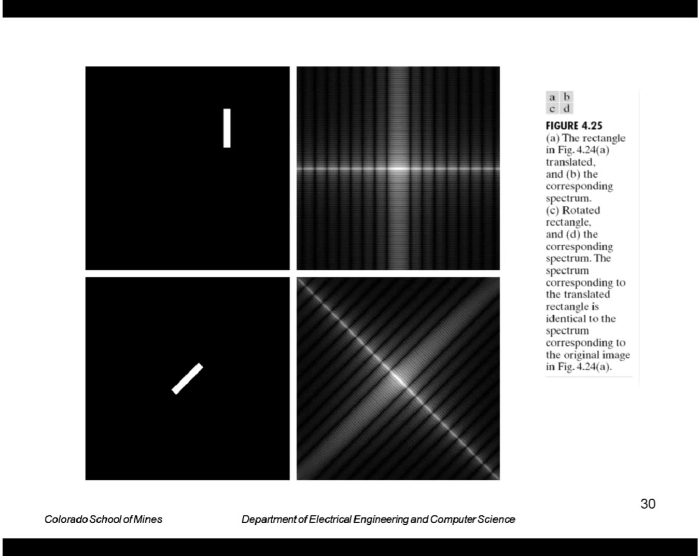So if we take the absolute value or spectrum, basically that component we multiply by is just wiped out. It's just a 1. So the spectrum looks identical to the transform when the object was not shifted. If we rotate the object, let's say by 45 degrees, that rotates the spectrum by the same amount.